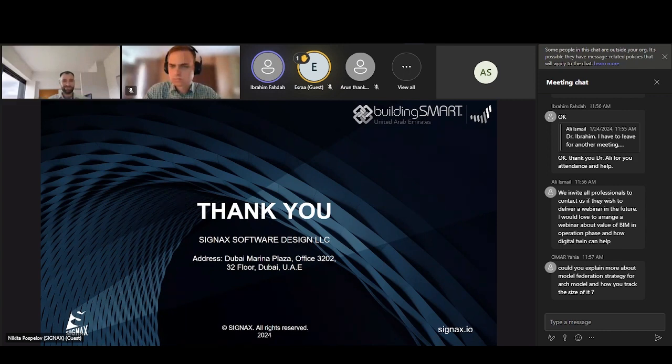All right, thank you. We'll take one last question quickly, from the chat. It says, could you explain more about model federation strategy for the architectural model and how you track the size of it? Just in the beginning, before the project, we create BEP and EIR documents that divide the project by BIM model files, and we started approximately. For example, we divided by building sections and building floors. But when we saw that, for example, facades or some other disciplines had too large a size, we decided to update the BEP document and divide them into additional files with less size and more accountable during the federated BIM model creation.